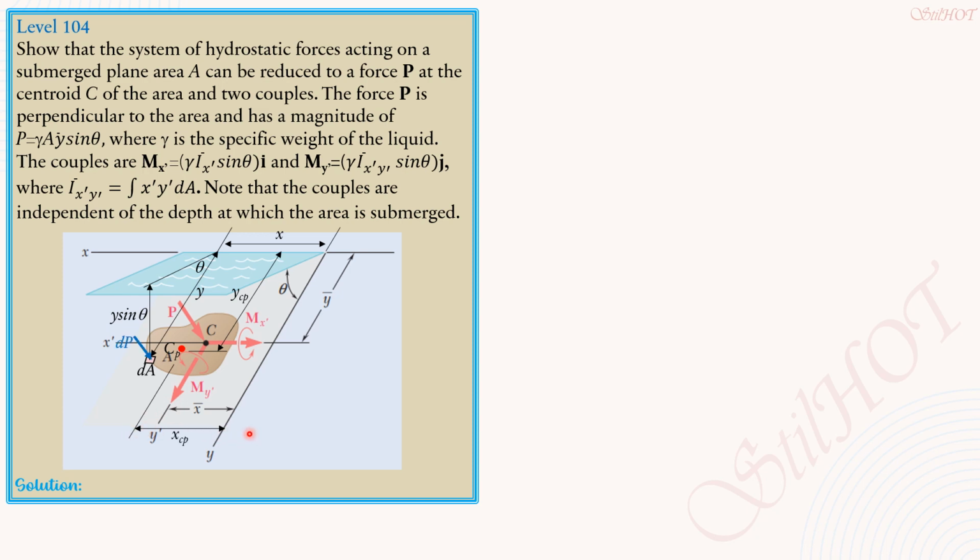Likewise, the differential force dP acts perpendicular to that differential area. This distance of the differential area from the y prime axis is x prime, and its distance from the x prime axis is y prime. So dP is pressure times dA, where pressure is specific weight gamma times vertical distance y sine theta. So dP is gamma times y sine theta times dA.